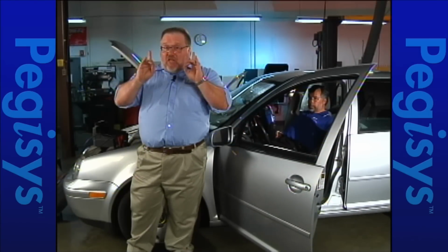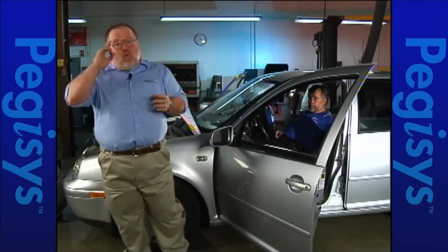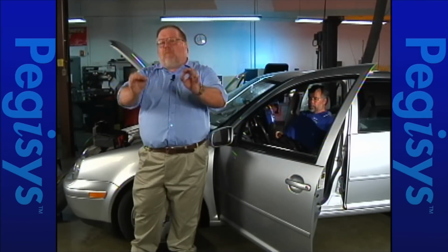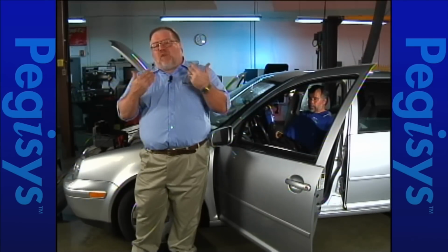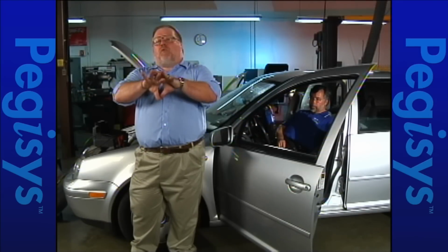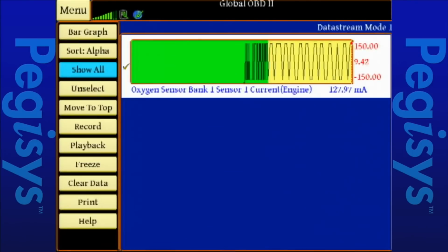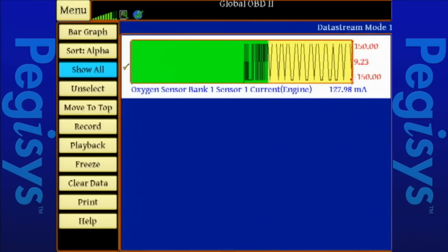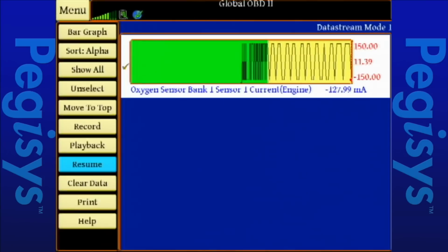Now, the key thing to remember here is we've diagnosed a problem that we weren't necessarily expecting to find. Remember, when we started off here, we were looking at a catalytic converter code. But as we said, you have to look at a catalytic converter code in context with what else is going on with the car. You never want to replace a catalytic converter until you make a determination as to what's going on. All right, Steve, that's good. Let's go ahead and bring it back down to idle.